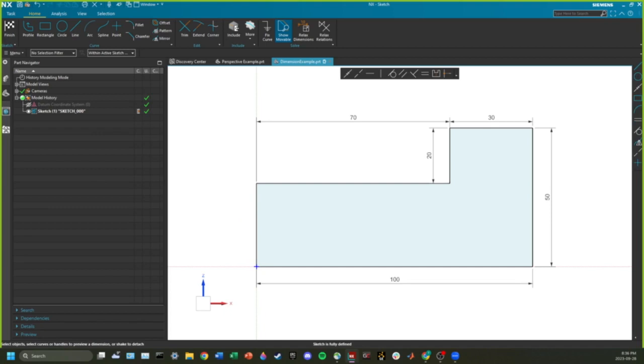If I know that I go up 50, I go down 30, go down 20, that last line is going to be 30, unless I said otherwise. From looking at this, I can assume, because I'm looking at it in orthographic view or from like one plane, that the line which is 70 long is going to be perfectly horizontal. And as such, there shouldn't be a change. If I said there was a change, then I know that that line isn't actually perfectly horizontal.